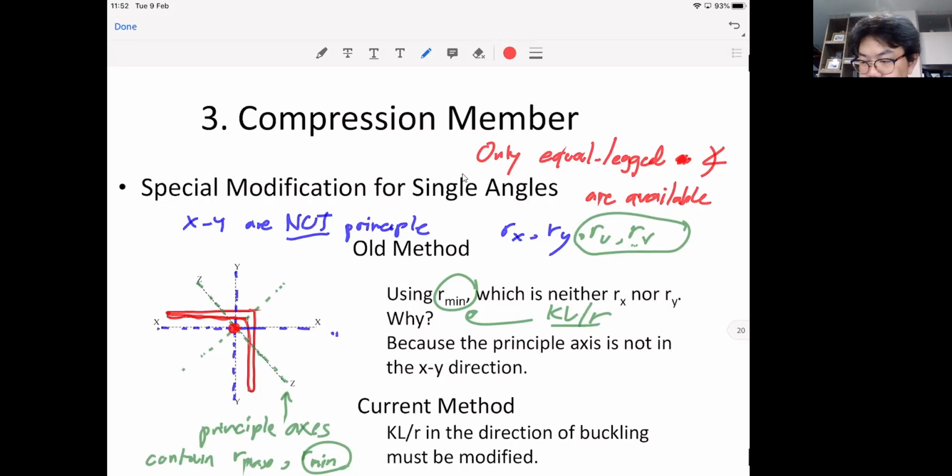That is so true. So that means one thing, because we cannot put the load through the air, right? We need to transfer the load onto the member by physical means. So your angle will have to carry the load from the support by itself, which means that it will create the problem that we call eccentricity.